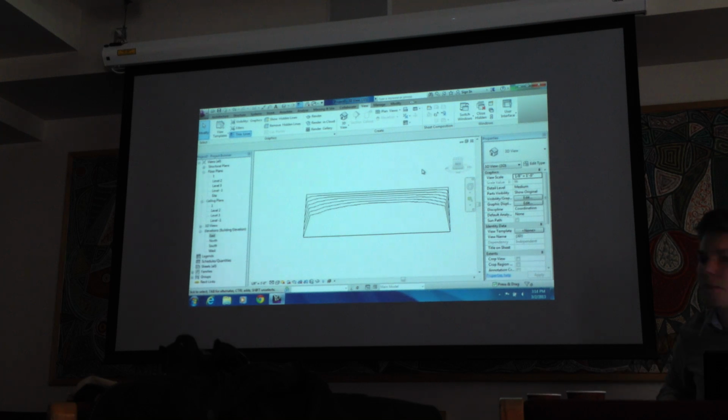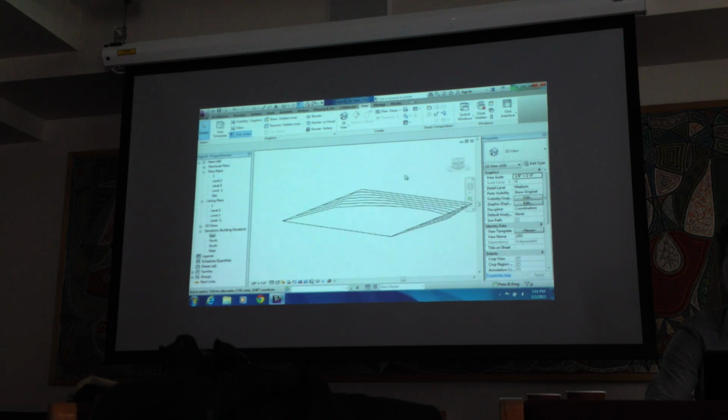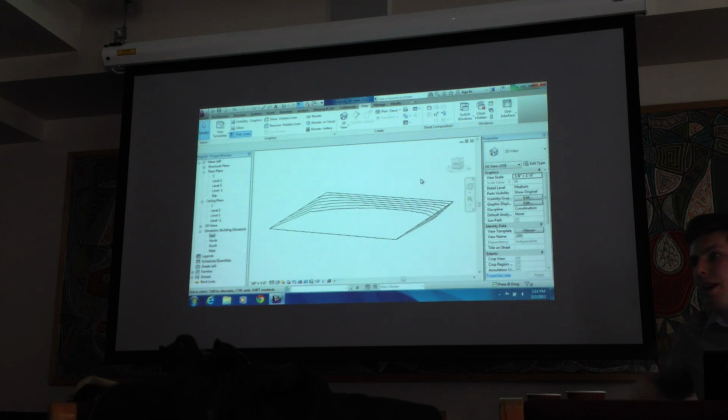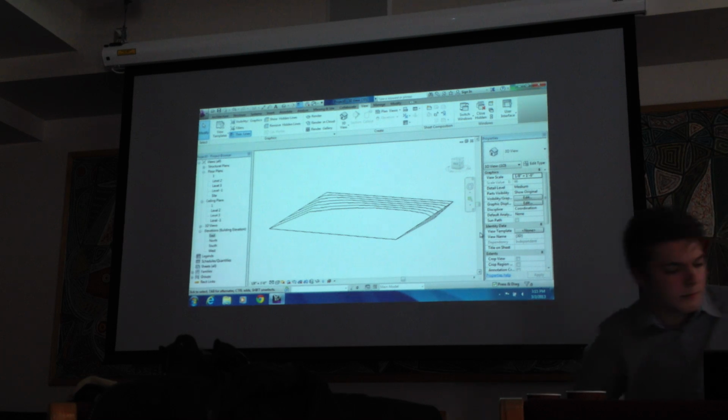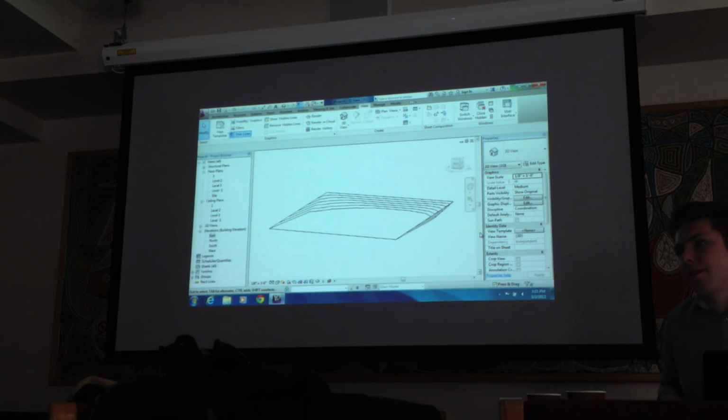What are those lines? Like the lines you just created. Those were the topography lines. They automatically create when you create your site. So each line right now represents a foot raise in the site area. So this is a 0 marker, this is 1 foot, 2 foot, 3 foot, going up to 6. You can change how that works in the view option category. I'll go through that later on. But it's just showing where the site raises or lowers.